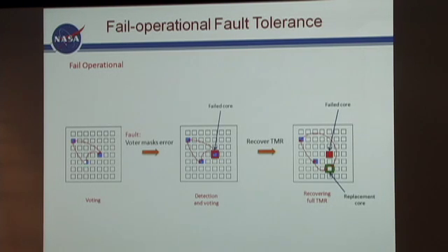So if we want to increase the reliability of that, we can triple modularly, redundantly, run the filter. We feed the same inputs that we would normally feed to one filter. We feed them to all 3. And then the results come out and they get voted. And we know that we can do that because the filter is a function.